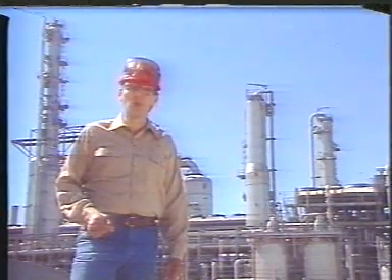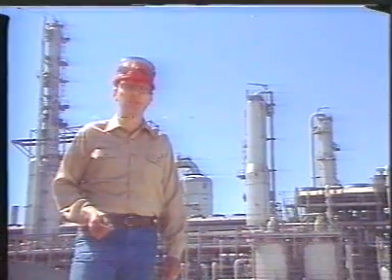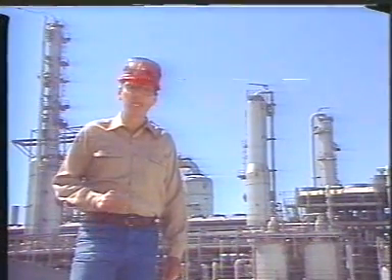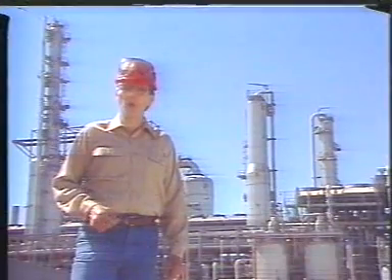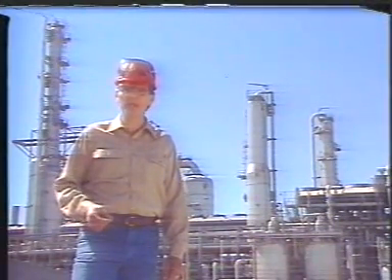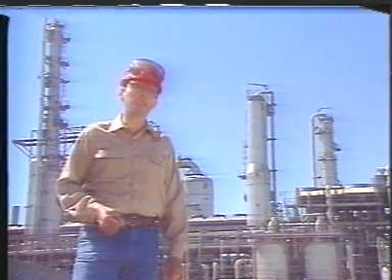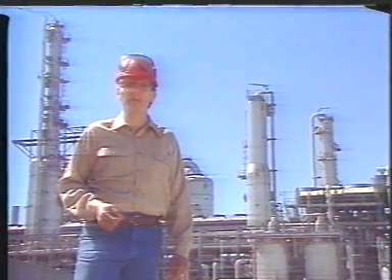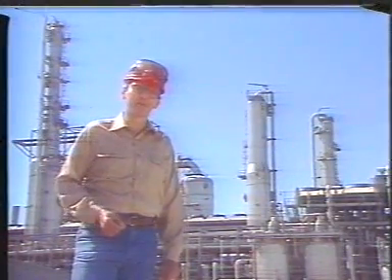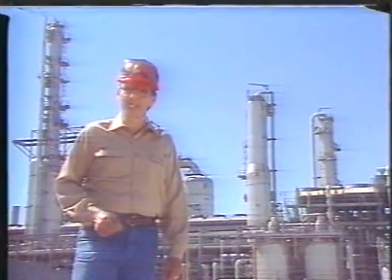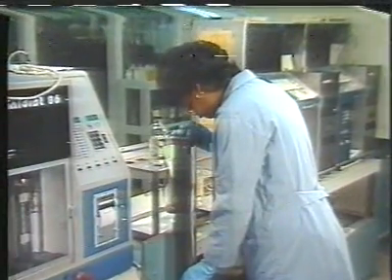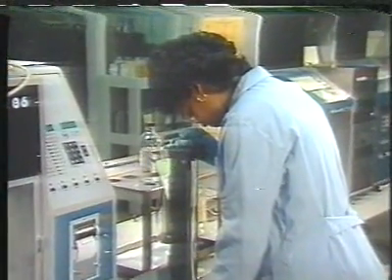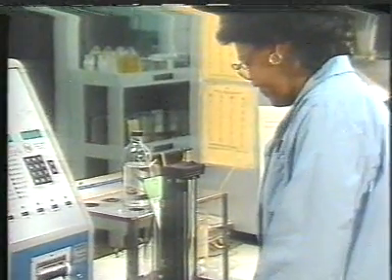Setting specifications for products allows us to control the type or range of molecules that are included in any one product. To determine product purity, we use boiling point tests or actually measure the percent of heavy and light key components in the product. Other specifications are set for flash point, API gravity or specific gravity, and color. Products are periodically tested to make sure that they are meeting specifications. When products are off specification, a change must be made in tower operations to bring the products back on spec.